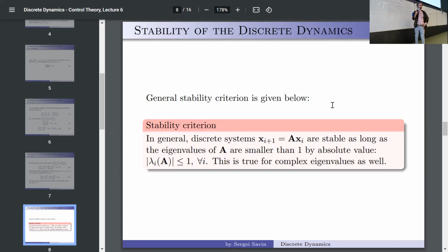So for continuous time systems, this is the part where the system is stable. And this is the part where the system is marginally stable. You get the idea, right? This is where, for continuous time systems, the real parts of the eigenvalues are 0. This is the part where the real parts of the eigenvalues are negative, so stable.